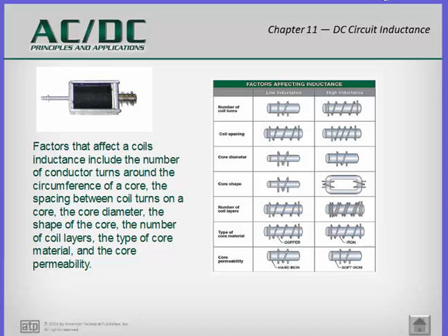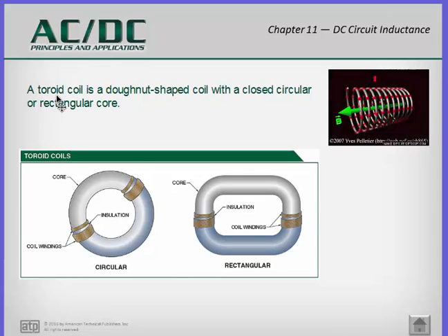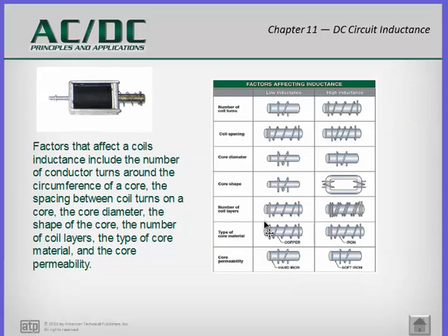There's a certain type of magnetic core called a toroid, and due to the physical structure of this type of coil, the magnetic field remains within this circle. It does not escape this circle. Whereas if you had a coil like this, then the magnetic field is going to come outside of the coil as it comes back into the south pole of the magnet.